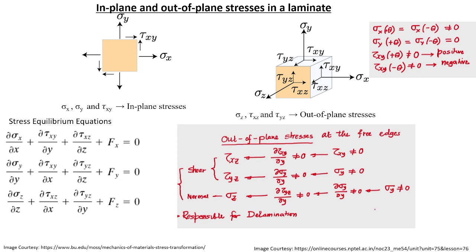So, in conclusion, we get the stress in z direction, shear stress in xz, and shear stress in yz directions, and these are all known as the out of plane stresses. Now, these out of plane stresses also depend on the in-plane stresses. It is already defined in the classes how it depends on them. But in conclusion, the shear stress in xz direction depends on the shear stress in xy direction, which is an in-plane stress, which we already know how to calculate.